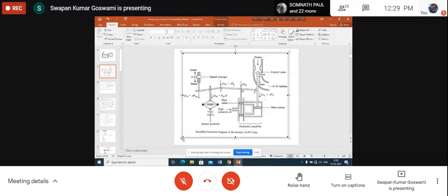No, it will not always. It is synchronous speed at steady state, but during the transient period, during dynamic condition, dynamic condition means some change in load, some increase in load, some decrease in load, some increase in input power, some decrease in output power. There, obviously, speed cannot be synchronous, because if the speed is synchronous at this frequency, then how will delta vary?